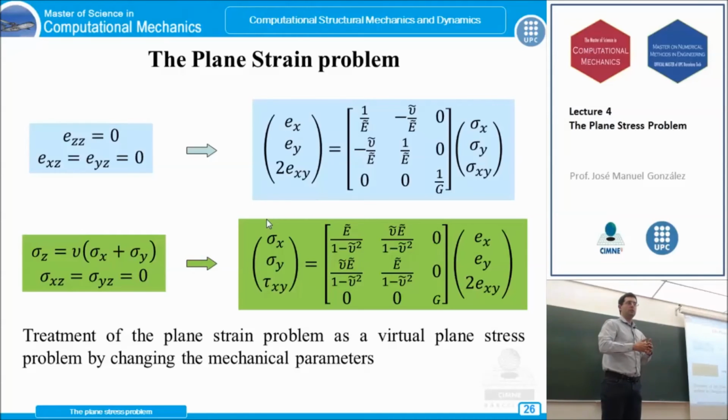Now we can do the same thing for a three-dimensional problem or any problem you can imagine. It's a question of defining which are your components, your unknowns, your given problem data, and your physical assumptions, and making the same steps. This is the variational formulation I wanted to present now as a basic step in finite element modeling.